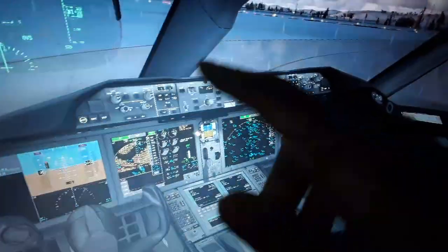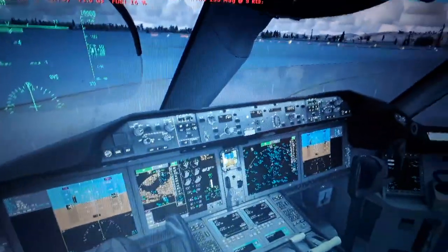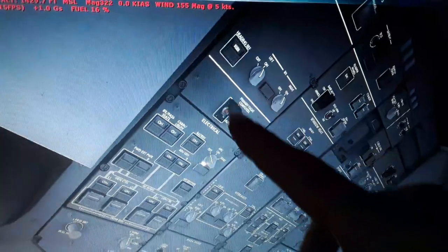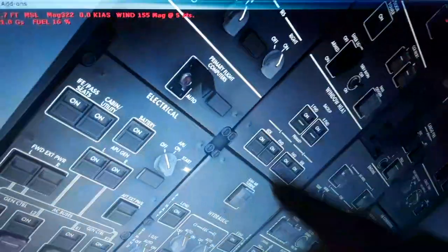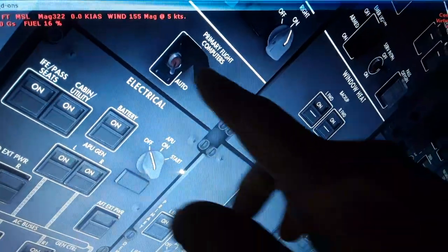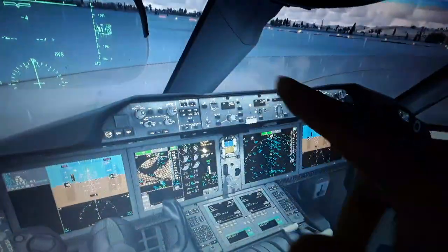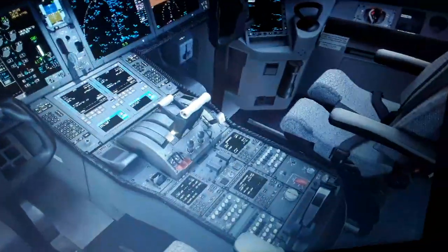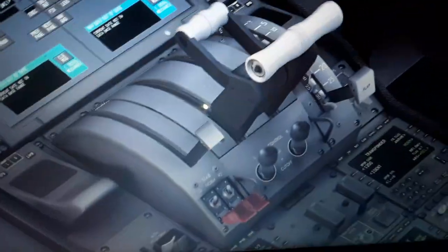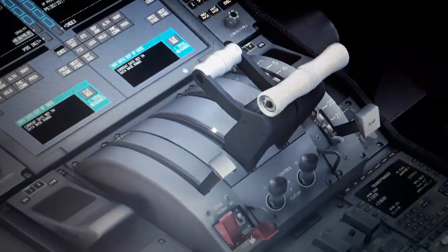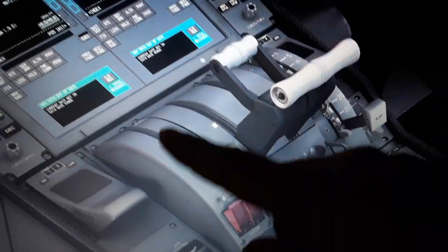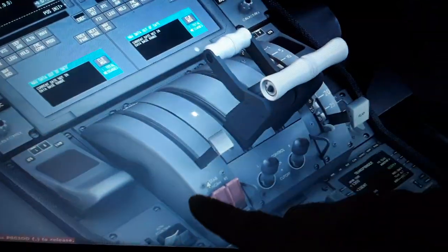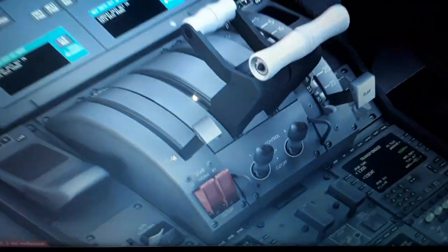We're gonna lose the auto trim function, so the autopilot, the flight control computers will be degraded from normal to alternate or direct mode or mechanical backup, like in the Airbus. So we're gonna lose the autopilot, and we're gonna have problem with the auto trim function. So we come down here. This for our Boeing 737 over here, 757, Boeing 767, Boeing 777, and Boeing 787.